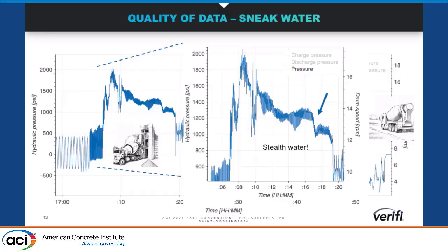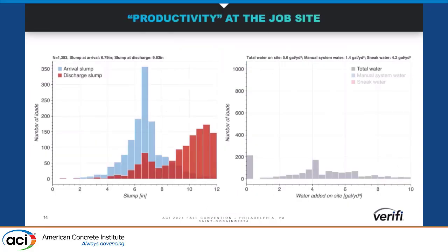So you can help to retrain drivers, retrain batch people, but we can back calculate what water actually went in there, right? I wouldn't put that, so there's a lot of things around the accuracy of that water. I wouldn't put it on in terms of from a litigation standpoint, but it's good enough to start to change behavior for your drivers, for your operations. You'd have to do a fluorescence test or something like that to get a little bit more.